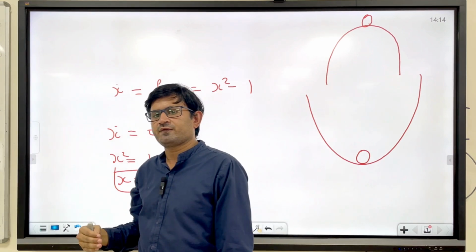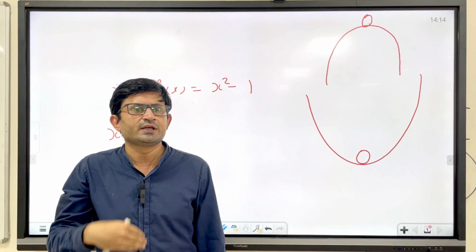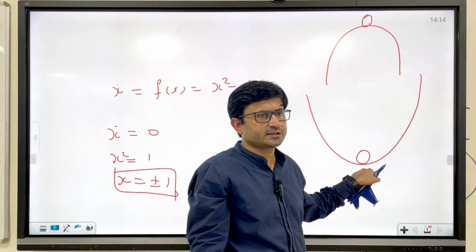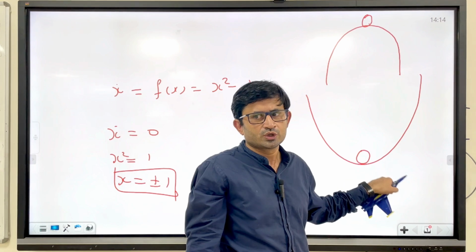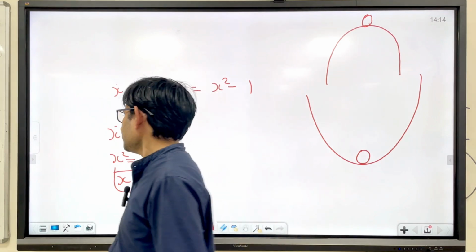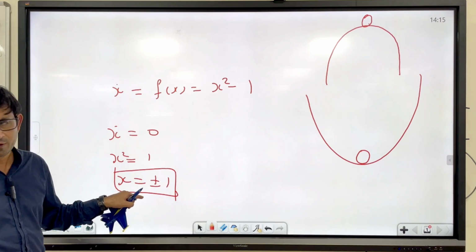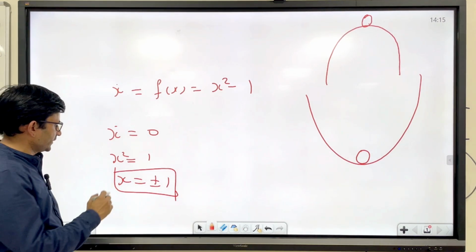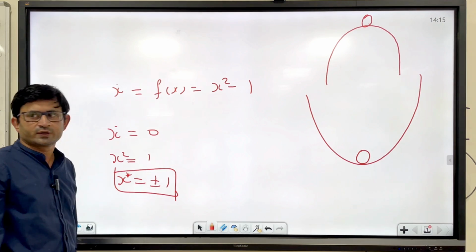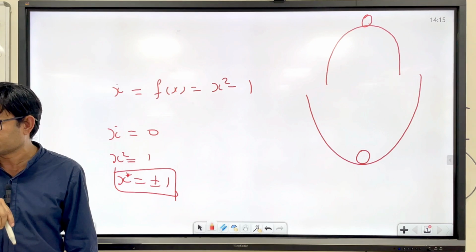And there is also one kind of neutral stability at which the system will achieve a new equilibrium point. Like here it is coming back to the original position, right? So in another case it is a new equilibrium point. Okay. So that is the neutral stability case. So now we have found out the equilibrium point. Then you can denote it as x star. Okay. Now around this equilibrium point we will linearize our system, right?